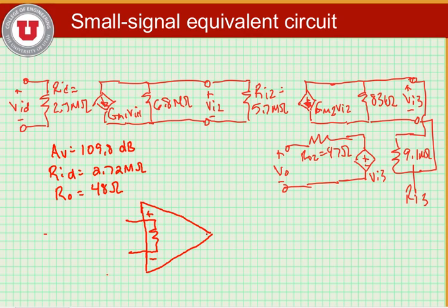So here we have our inverting and non-inverting terminals. Here we have a voltage-dependent voltage source, VDVS. So this is our voltage gain. And we have an output resistance. So this is Rout, this is Rin differential, and we have our nice, good voltage amplifier.